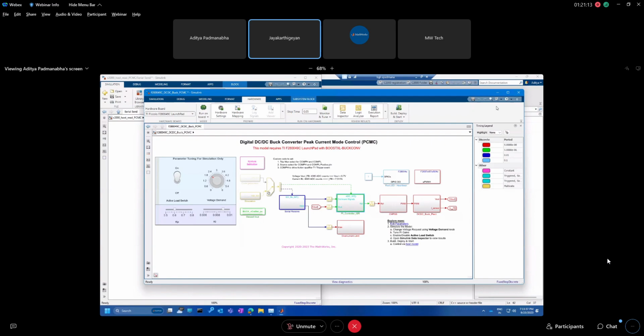There is a wide list of feature differences between these two. We have something called Connected I/O, which we have recently introduced in the C2000 Microcontroller Blockset when it transitioned into a product, and also some additional C2000 device support, like the latest F29x and F28x processors, which are supported in the blockset.